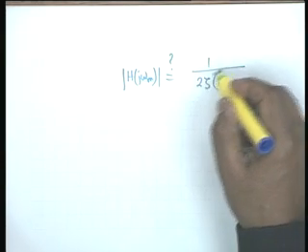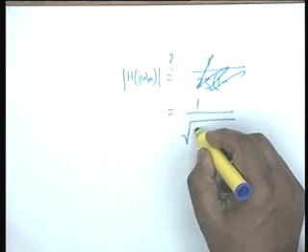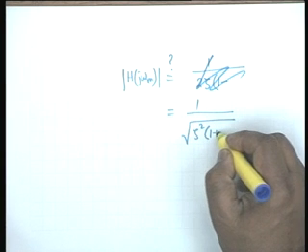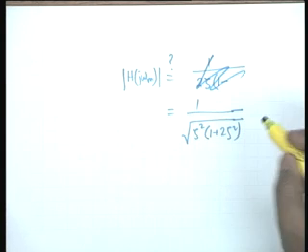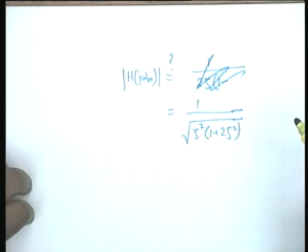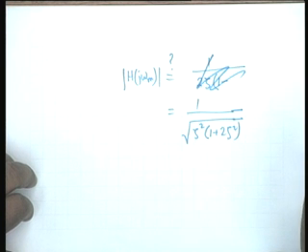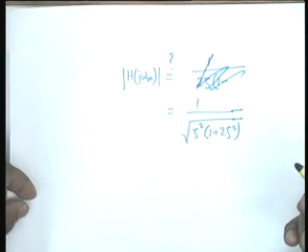Maximum value, no, I beg your pardon, is equal to 1 by square root of zeta squared, 1 plus 2 zeta squared. So unless you substitute here, you would not know whether there are 2 cutoff frequencies or 1 cutoff frequency. It cannot be said by inspection. Okay. So there may be 2 cutoff frequencies, there may be 1. Let us see what is true for this particular situation.